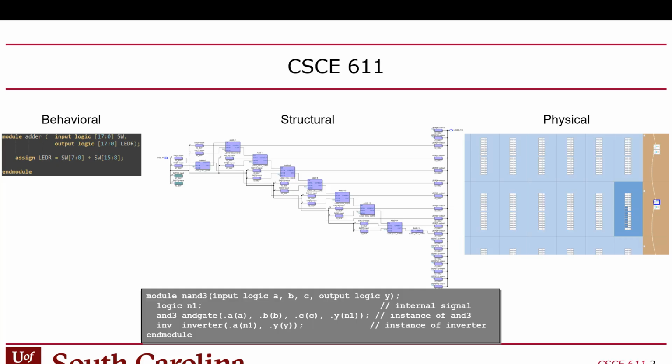That Verilog can either be behavioral code or structural code, meaning it can have logic expressions in it, or it can have components with wires connecting them. And then you can go into the RTL viewer in Quartus, and it'll actually generate a schematic for you. So this is machine generated. No one actually drew that.